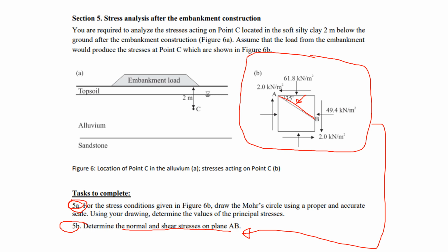From your drawing, you determine the value of the principal stresses. You don't need to calculate them using the formulas. I want you to get them from the drawings. I want you to practice drawing. Most likely you need to use the drawing compass and stuff like that, but this is what you need to do to get the full mark for this question.